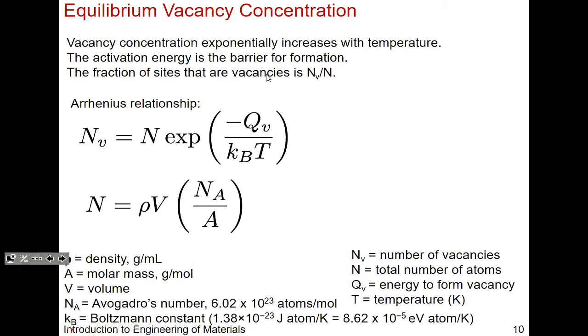Stoichiometrically, when we're discussing composition, we want to be talking in terms of atomic percent. Is it silicon 0.99, phosphorus 0.01, right? That's atomic percent. So depending on the scenario, we talk about atomic percent when it's convenient for us, or when we're dealing with the actual mixtures physically executing the work, it's more convenient to deal with weight percent.